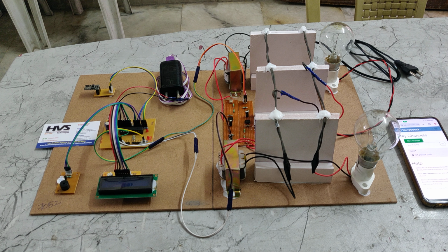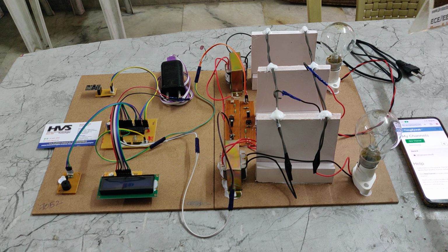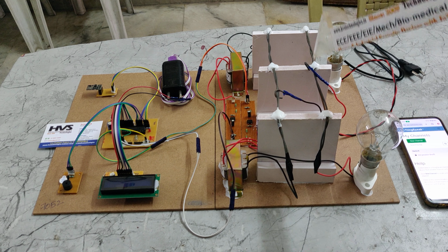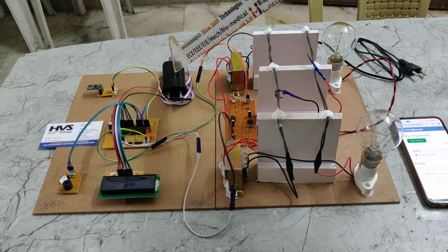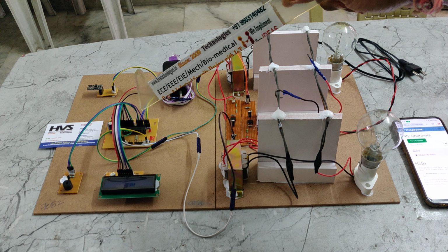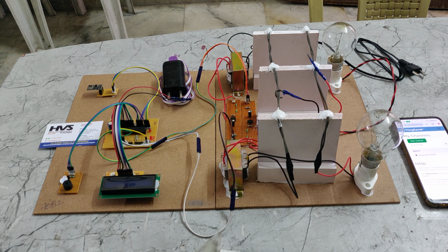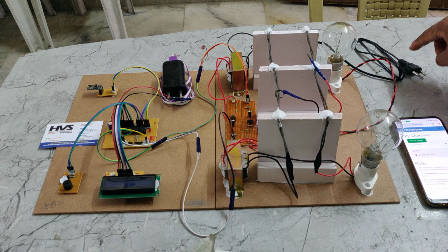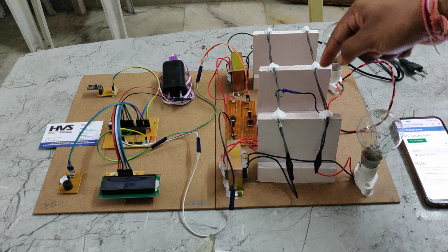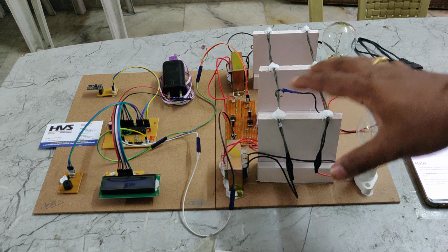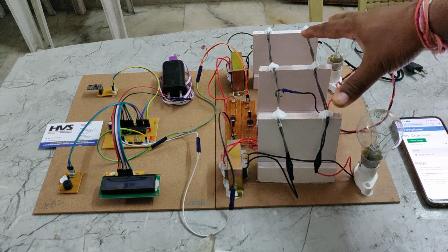Here we are providing mainly two power inputs. One is for these overhead lines, the transmission in the street levels, and this is the adapter for the power supply of this PIC microcontroller. While demonstrating, when we provide the power supply, check this very safely, these are directly 230 volts passing lines, so don't touch anywhere on this board.